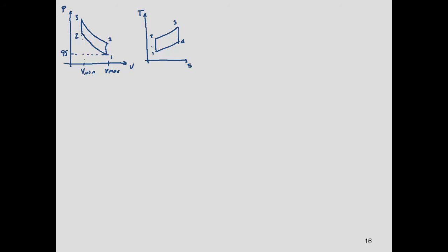Okay, since this is the first video, we're going to do it step by step. We are asked to get the net power at 2500 RPM. So we can start by writing the expression. The net power will be the net specific work per cylinder, times the number of cylinders, times the speed. Since the speed is in RPM, we need to convert it to 1/second. So that will be divided by 60 for the seconds, and 2 because we have 2 revolutions per cycle.